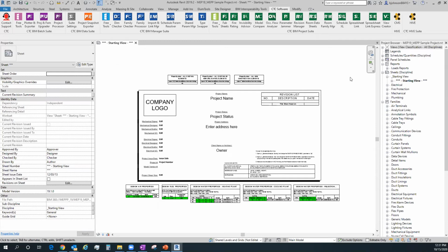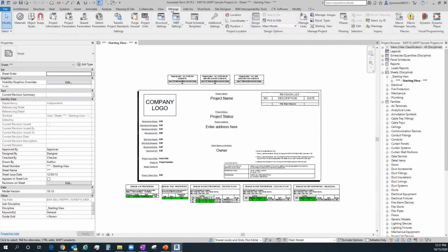So when you start hitting those kinds of numbers, usually Revit's trying to calculate what's going on with the warnings and figure out what it can do with them. And that causes Revit to really stumble. It's extremely slow. So if you don't know where your warnings are, typically your Manage tab on your ribbon is where we want to go. And then towards the right end, there's an inquiry area. And right above that, there's a warnings.